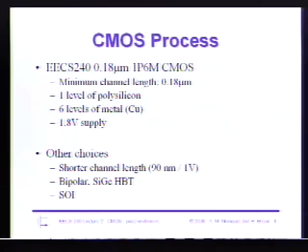So I've modified that model slightly. I noticed that the output impedance of that model was a little bit too nice. I wanted to make it more realistic, so I've made the output impedance have breakdown effects. We'll talk about that next lecture, or the lecture after that. But other than that, it's the model that comes from him, and there's a big header in the file that explains how he put this model together. If you're interested, have a look at it.